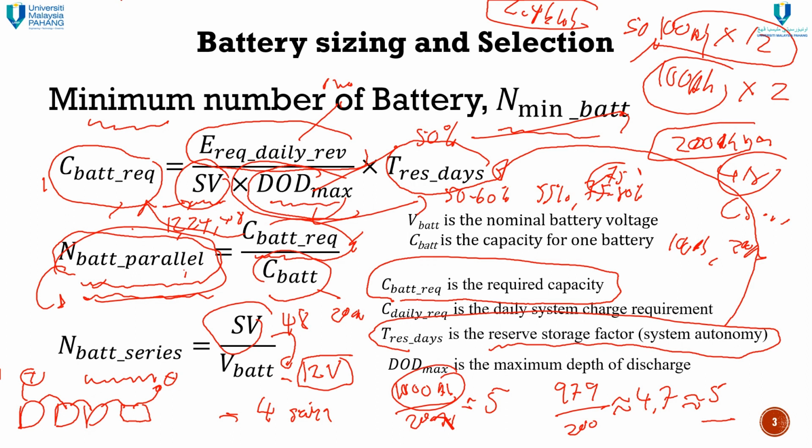But if you try to connect in parallel, with this battery you connect here, then connect here. At the same time, this one goes to the load, this one goes to the minus, but you parallel. So why is parallel dangerous? Because of the loop, it's a closed loop.